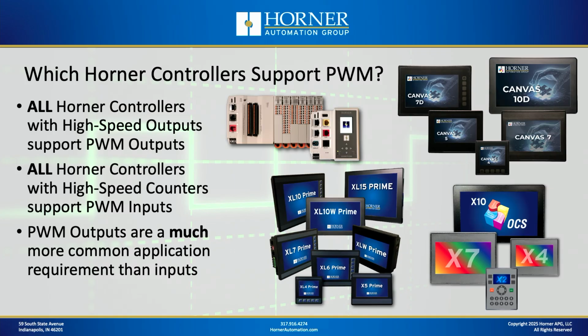Okay, now which Horner controllers support PWM signals? Well, basically all of them. As long as they have high-speed outputs, as long as they have high-speed inputs, then they can do PWM on the output side and they can do PWM on the input side. Now, keep in mind that PWM outputs are much more common in various applications in machine control than PWM inputs would be. So we're going to show you how to do both, but you're going to use PWM out much more frequently.